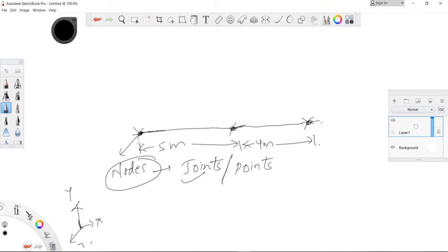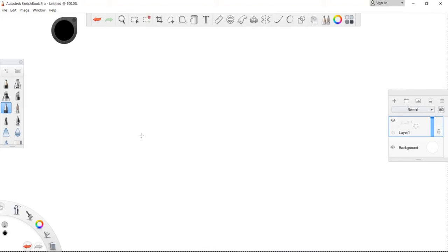How do we define the nodes? We will see here. So let me delete this and deselect it. Okay, so we got the origin here. This is the positive X, this is the Y, and this is the Z. It is very important to understand your axis system when you model your structure, so that you are modeling your building in the right direction. Okay, so this is your origin. We always define our first node at the origin. So we got the origin at 0, 0, 0.